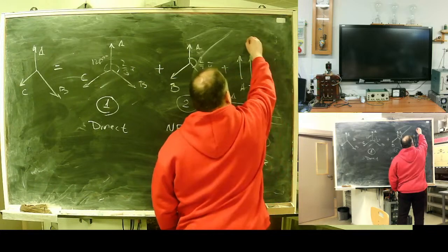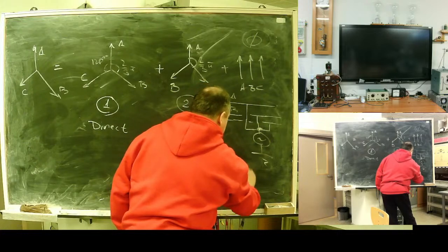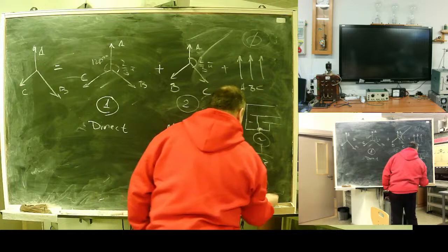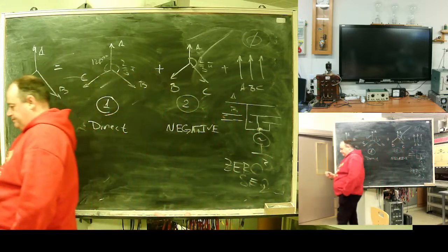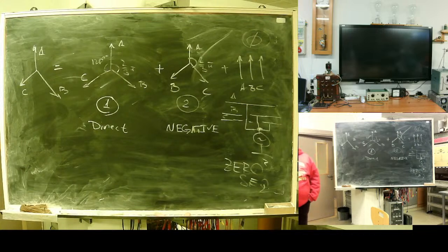Imaginary network called zero sequence network. This is needed to represent ground current or current in neutral wire.